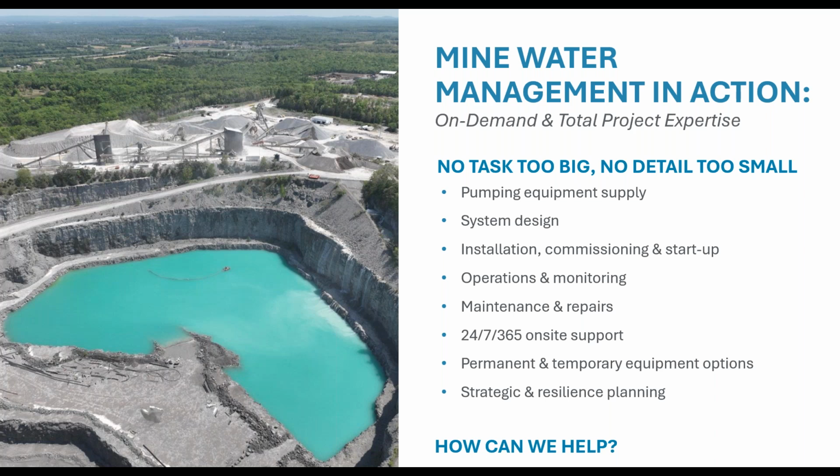It was actually more upstream. The larger vertical turbine pumps that were in that smaller mine void, kind of the main sump, were fitted with some duplex stainless steel materials and special coatings to help it withstand the sediment a bit better.